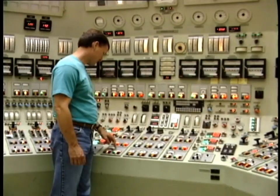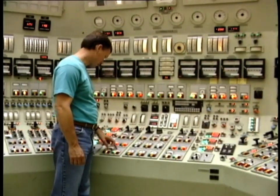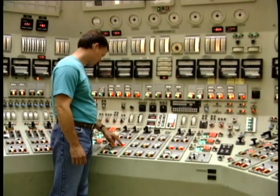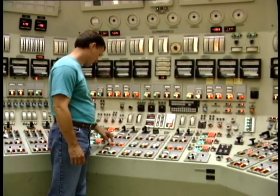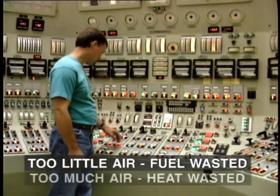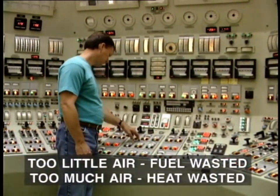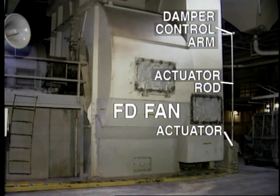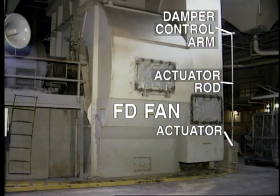So in order to obtain optimum efficiency, the operator has the difficult task of precisely controlling the amount of air supplied to the boiler. Too little and fuel will be wasted. Too much air, and heat will be wasted. To assist the operator in this task, specific instrumentation and control devices are installed on the boiler, as we shall see in the next module in the series.